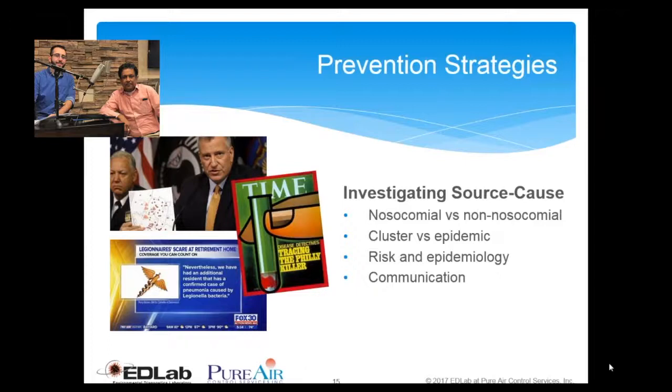And then the risk factors must be analyzed by analyzing the other environmental conditions and other supportive factors of Legionella, and epidemiological data, if available, must be analyzed in order to respond. If you have a previous episode of Legionella, a previous cluster or epidemic, what was the outcome and how was that addressed must be taken into account in order to respond again if a new episode happens.